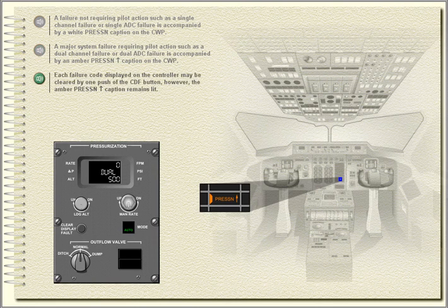Each failure code displayed on the controller may be cleared by one push of the CDF button. However, the amber pressurization caption remains lit.